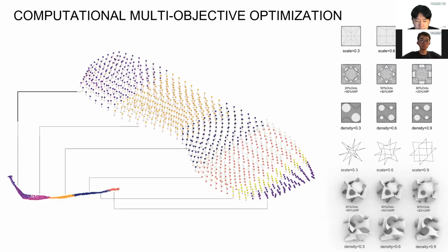Then we took the 6 optimal zones and tested them with various proposed optimal lattice units to be distributed in each segment. Various lattice units were picked to suit the temporal pattern, ranging from an auxetic structure that provides cushioning and bouncing to a solid minimal surface shell structure that provides resistance in the pronation process.